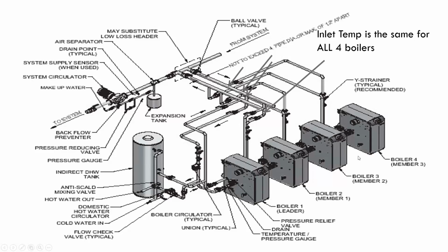Just for argument's sake, if this was my 30 and I was taking 3 instead of the picture of 4, but if I had 3 10-gallon-minute pumps, what would be the flow rate right across that common pipe when everybody's running? What should it be? 0. Exactly right. So in that case, primary and secondary match, they equal, there's no flow through the common. So all of that 170 gets heated, 20-degree rise, comes out at 190, matches the desired flow rate. Stage control says, hey, you met, wait, perfect. That's primary, secondary. That's with multiple boilers. It could be with multiple chillers.